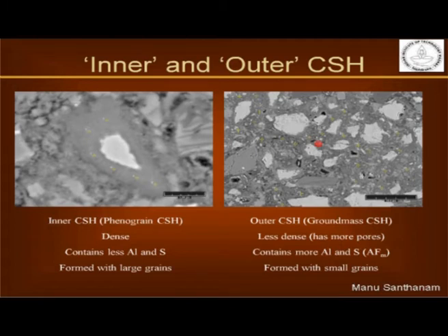inner CSH layers. And this happens typically at a much later stage as opposed to the outer CSH formation. So the early strength that you see at 1 or 3 days is just because your outer CSH is forming very fast, okay. The later strengths are because your overall structure including the inner CSH is developing and reducing your porosity slowly, okay. So there are several distinctions which I am not going to talk about here because it is not probably within the scope of our discussions.